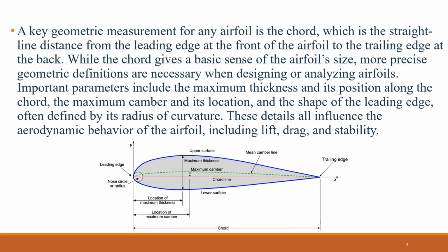For example, increasing the camber near the leading edge can raise the maximum lift coefficient, which is beneficial for lift generation, but it also increases the pitching moment, affecting the stability and control of the aircraft.